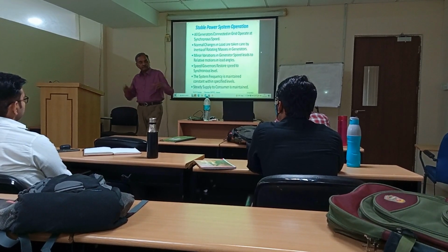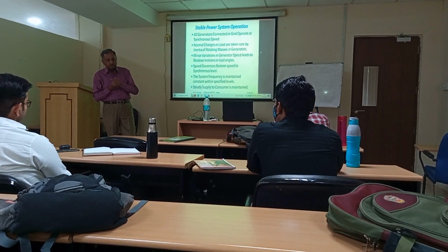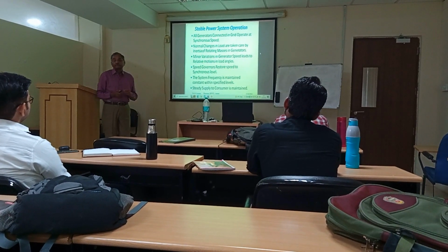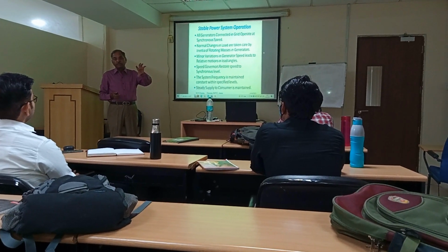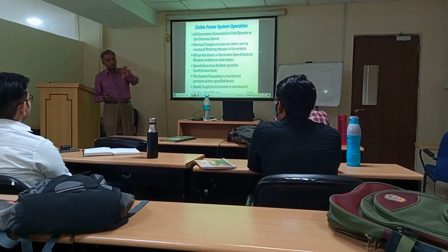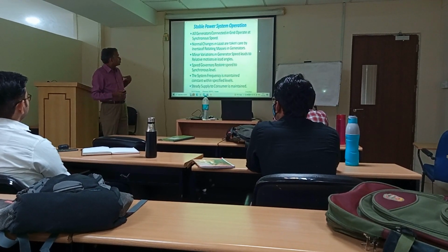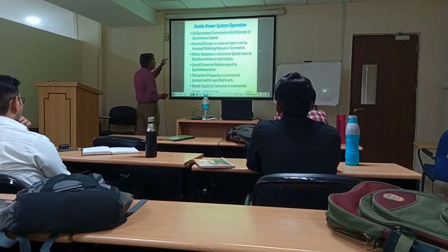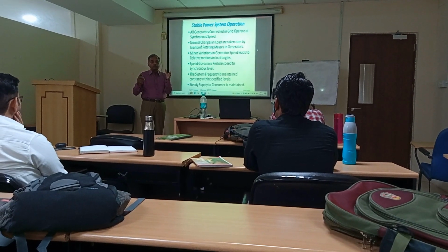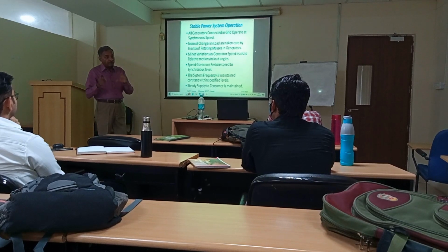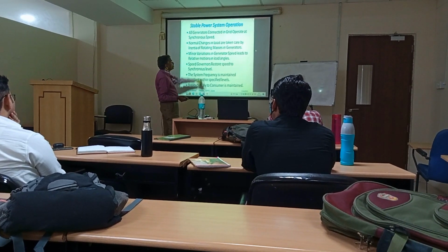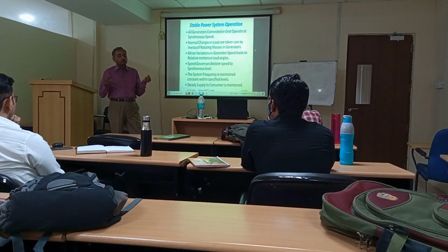Basically, the mass is in the turbines, hydro power turbines. So they are huge masses. When these masses are rotating at a speed, if they lose energy, they will slow down. Energy is proportional to the square of the speed. If they slow down, the synchronous speed will come down. If you unload them, reduce the load, then they will speed up. But in doing so, they are able to manage the small changes in the load.